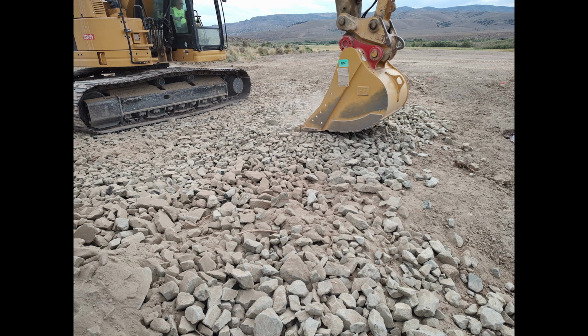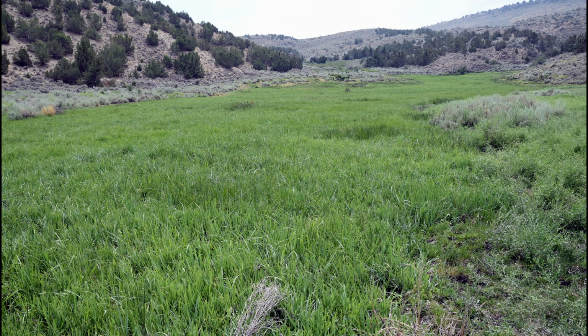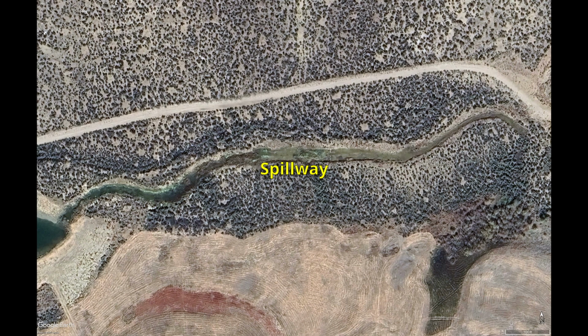This traffic had the potential of lowering the elevation of water in the fishing pond by lowering the elevation at the entrance of the spillway. We wanted to build a spillway as long and as wide as possible to create wet meadow habitat. While on the ground examining the area where the spillway would be built, we identified a drainage along the eastern edge of the property, and this drainage was not eroding. This drainage would allow us to move water downhill from where the spillway would end into the river valley below